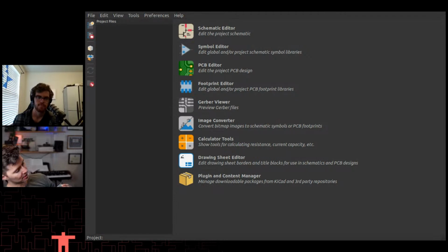it doesn't make sense to try some of this stuff at the beginning of your journey, I feel like. Because this has a switcher on here, and a switcher has inductors and capacitors and things like that. That can cause all kinds of craziness. Also, the package style of the RP2040, I probably wouldn't do that at the beginning. And then a crystal, or oscillator rather, it's fine. So I feel like recreating the Pico is not a good starter project simply because of the size of the ultimate components on there.